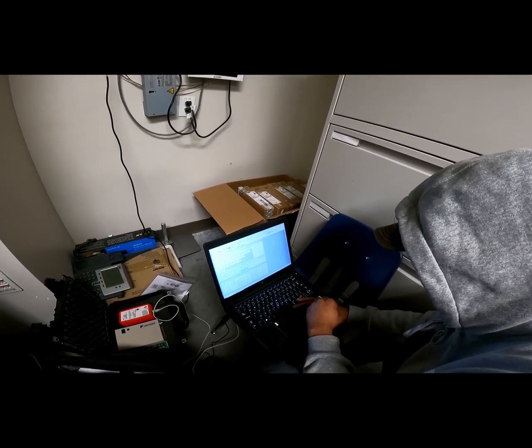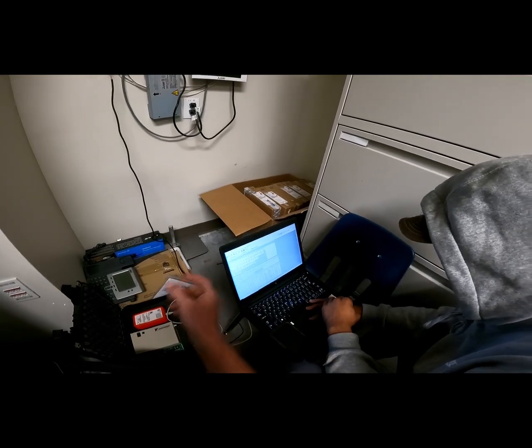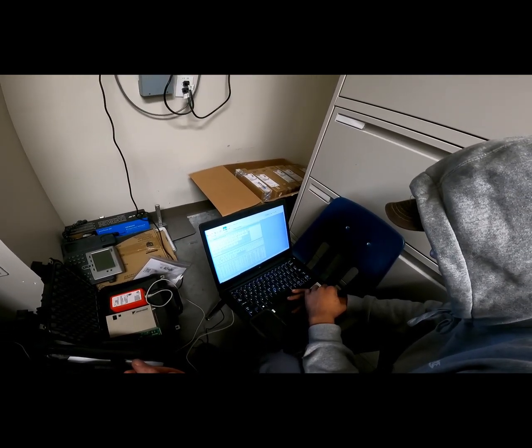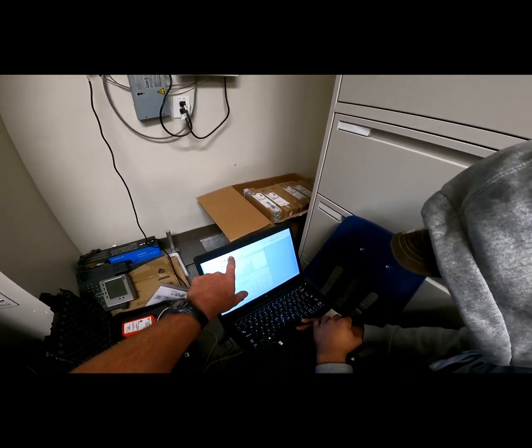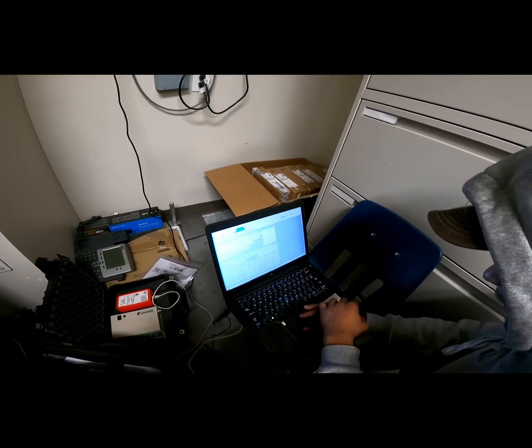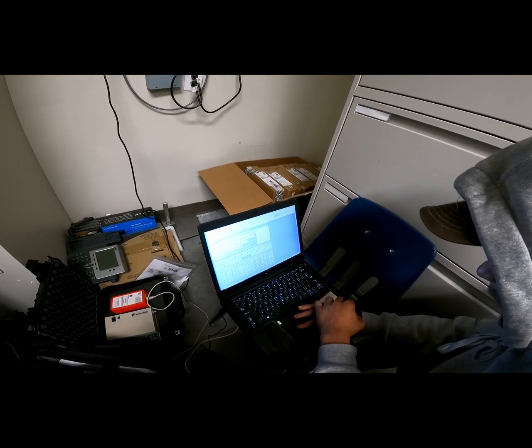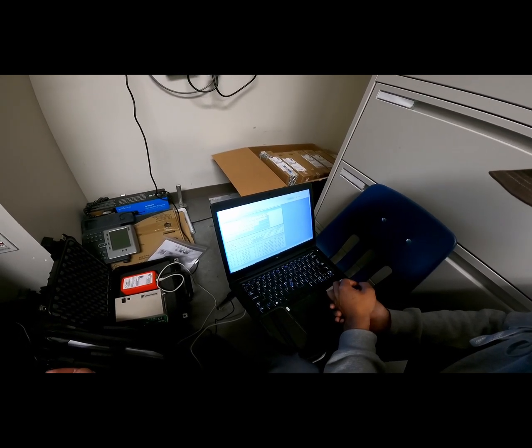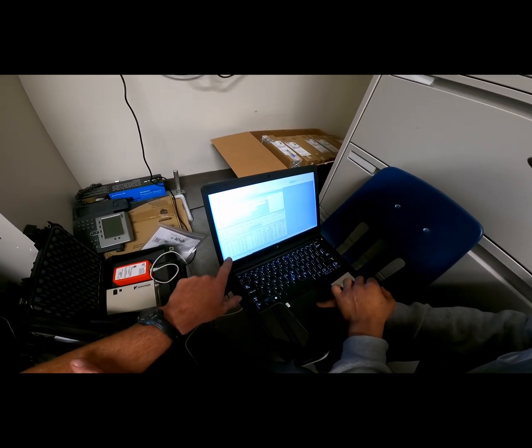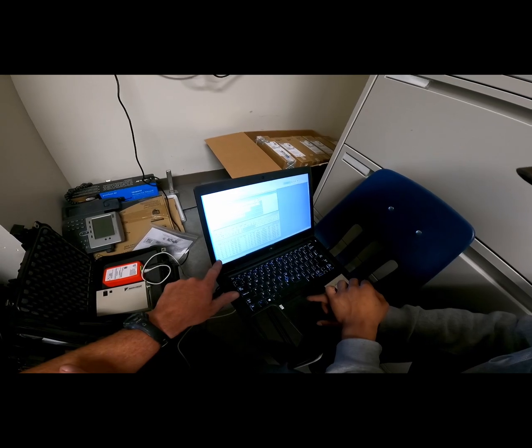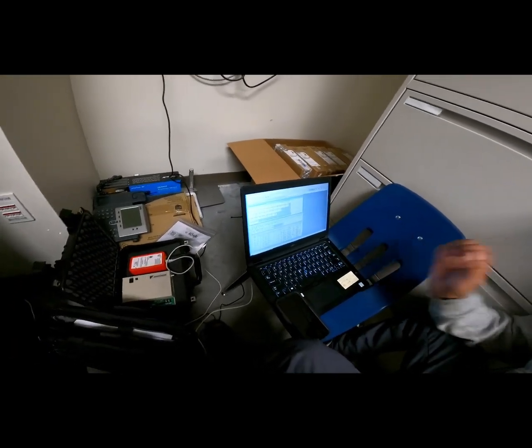All right, now that we've got this thing pulled up, we want to run it in test mode. So we're going to go up to drive operation at the top. Where's that? It's right here. And you're going to go to IC for indoor coil. Now, do you see the address numbers on each one of these units? It looks like we got 21 through 28. Yeah. You need to remember that.